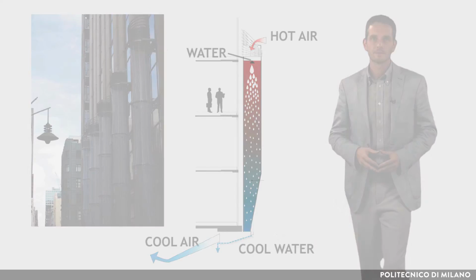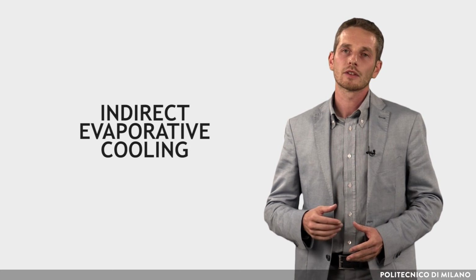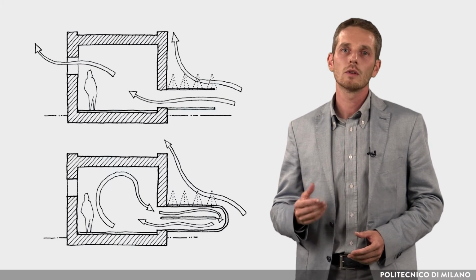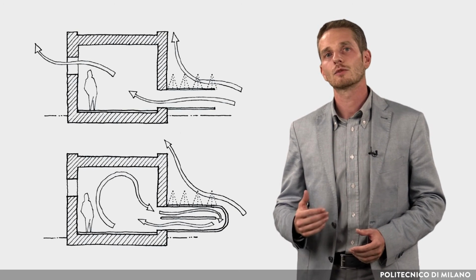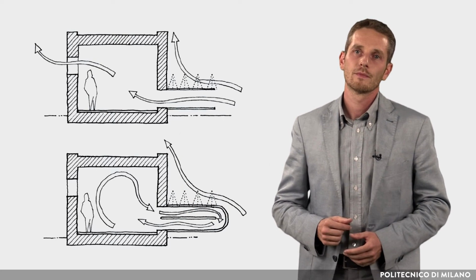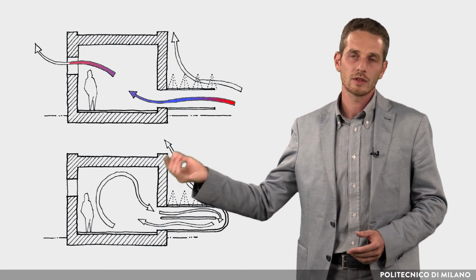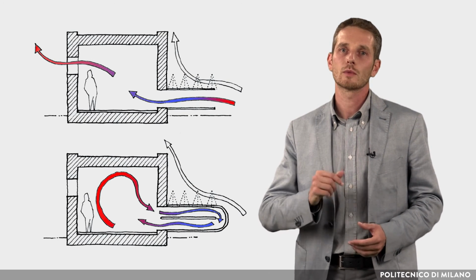In climates where the direct evaporation of water in an airstream would lead to a too high relative humidity, an indirect evaporative cooling can be used. With this technique, the air cooled and humidified by the process of adiabatic humidification is sent to a heat exchanger, which the ambient air to be cooled passes through. The air processed by the heat exchanger can come from outdoors in case of open circuit systems, or directly from the ambient if a closed circuit system is provided.